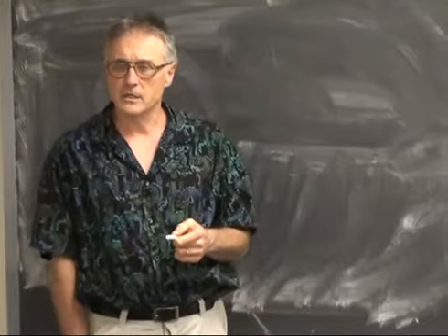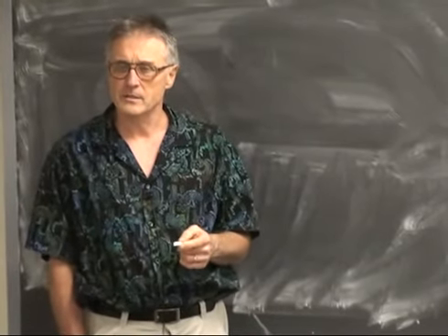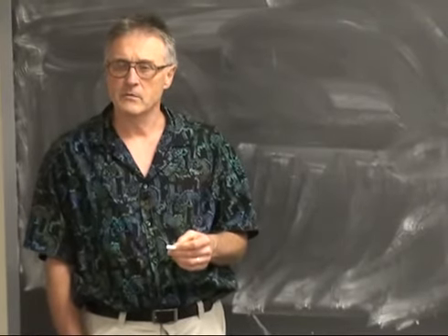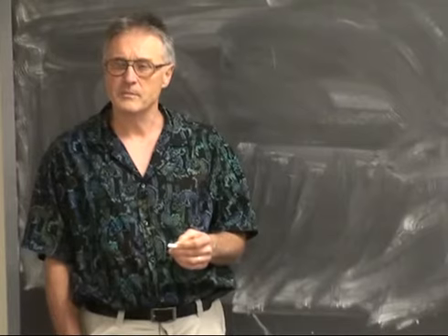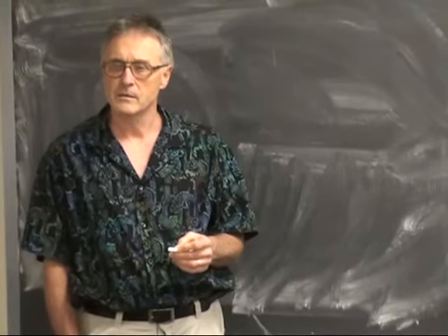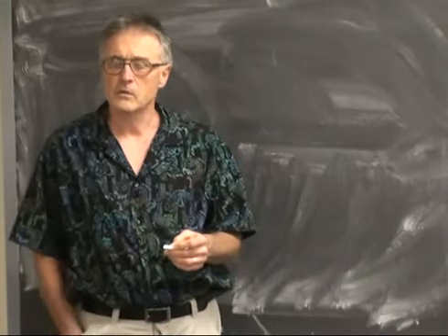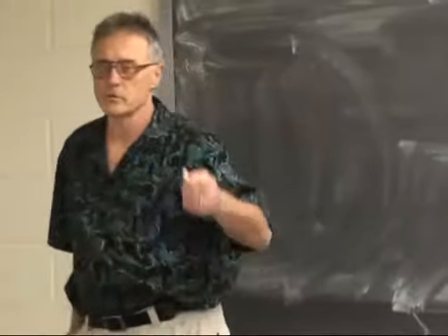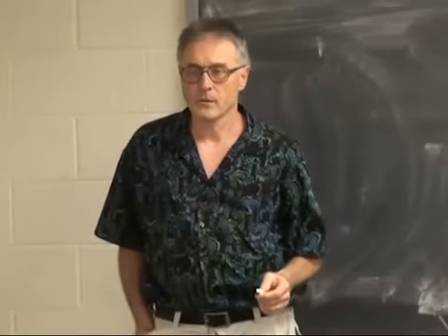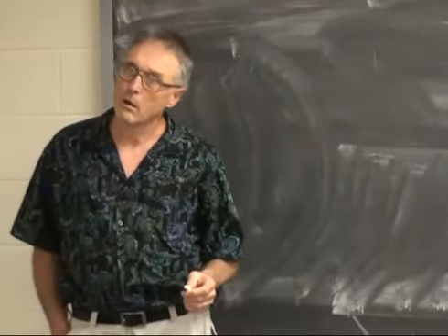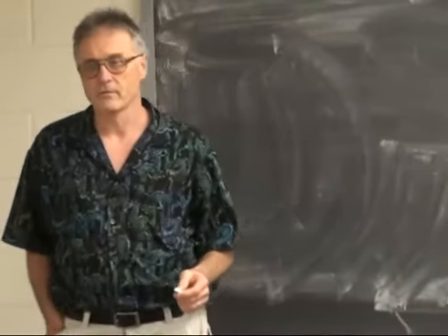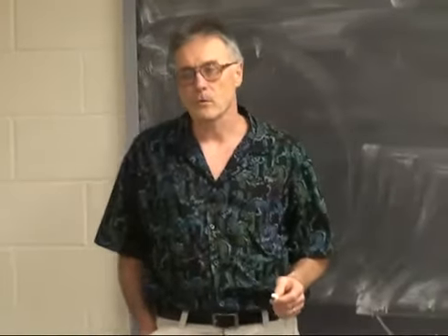So you had a long discussion last night, Darvin, I think, about generate statements. What happened with that? Was there anything you found obscure about generate statements? I wouldn't say it was obscure. The way the design was coded up made it hard to turn into a generate. The design was using multi-dimensional arrays to index multi-dimensional arrays. Okay, so simplification of the design was more important than unscrambling the generate.